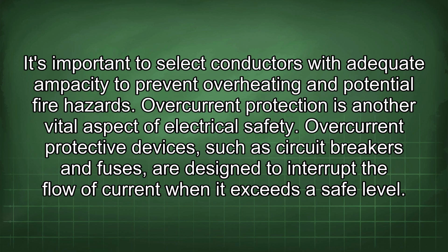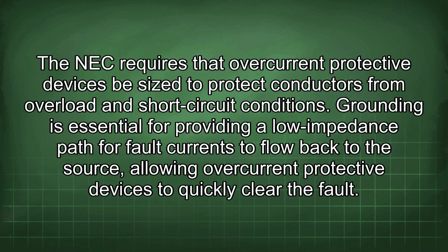Overcurrent protection is another vital aspect of electrical safety. Overcurrent protective devices, such as circuit breakers and fuses, are designed to interrupt the flow of current when it exceeds a safe level. The NEC requires that overcurrent protective devices be sized to protect conductors from overload and short-circuit conditions.